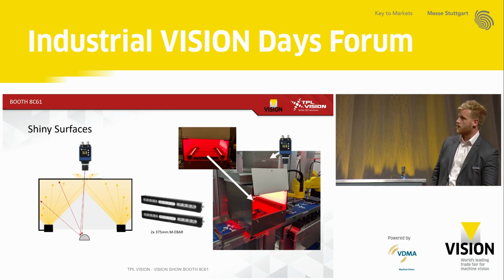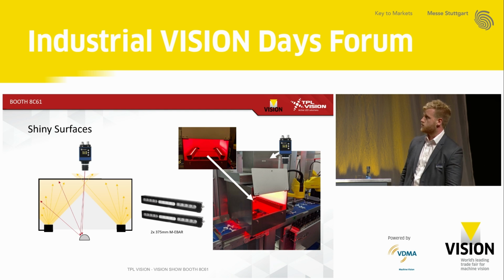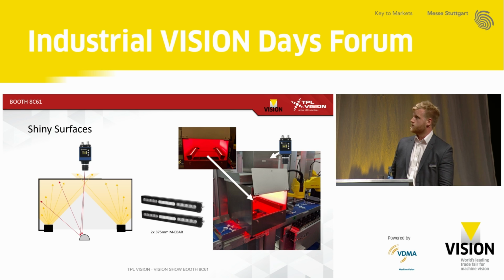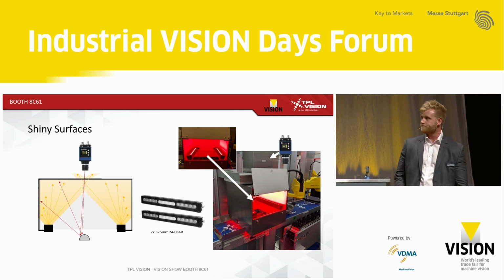So quite a common way that our customers get around this, which is also a cost-efficient way to create a big field of view illumination, is to use bar lights and illuminate up and create a dome effect. And this will be really uniform. It'll mean that when you have really uneven surfaces, regardless of which way they're orientated, you'll get a nice uniform surface on the top of that.